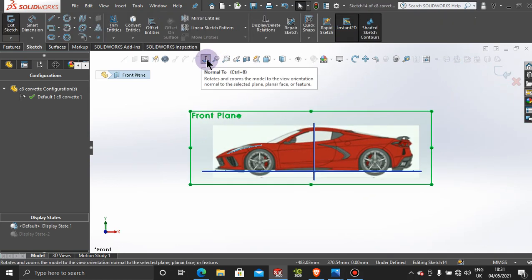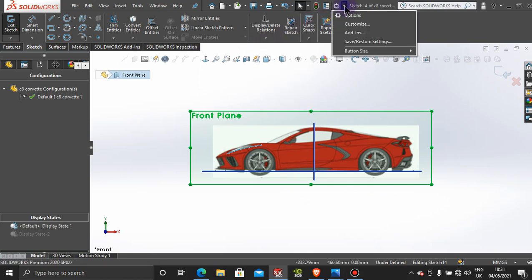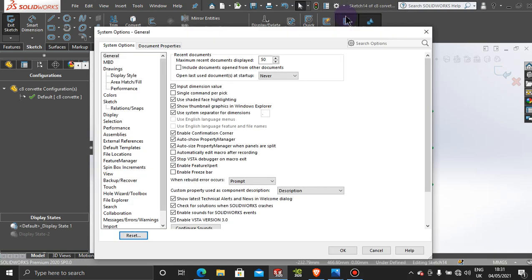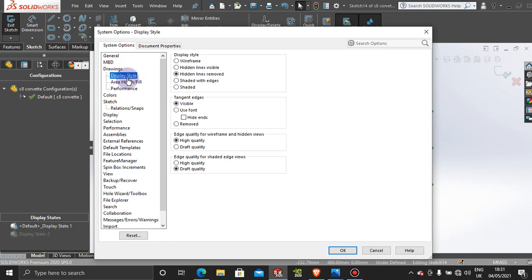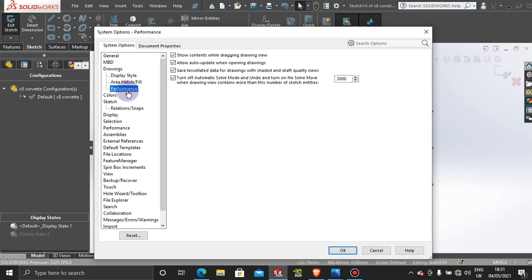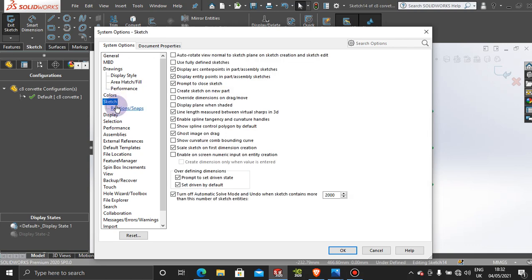and then we're going to press normal to profile. However, if you don't want to press normal to profile all the time, you can come over here in the options section, and then you can find something that says it will automatically drop to normal to profile without pressing the auto rotate. So there you go.